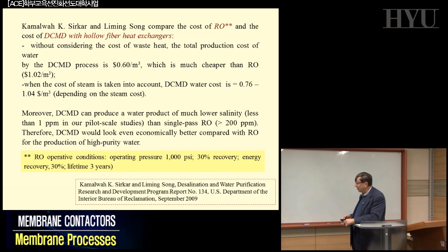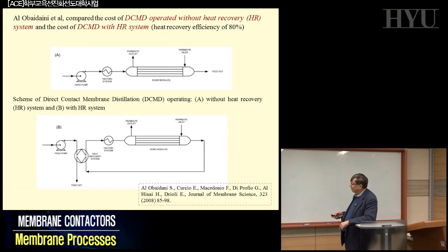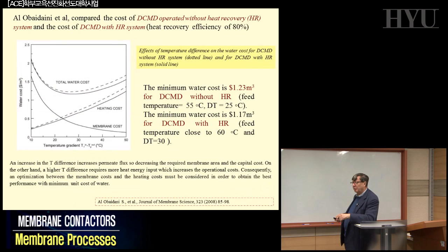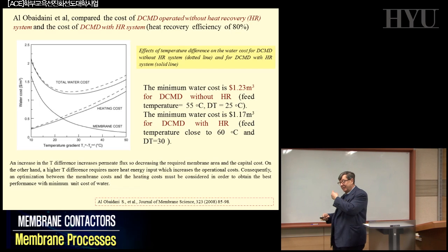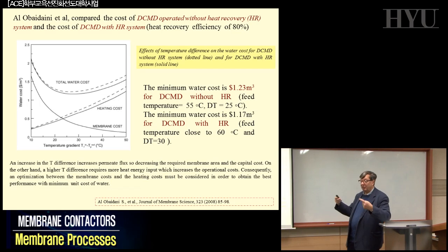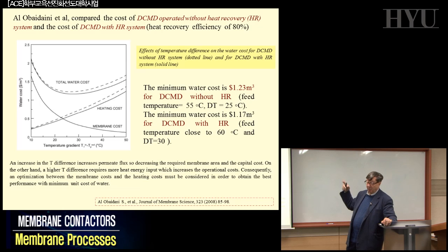And you will be able to realize what we were discussing the other time in terms of possibility to combine not only freshwater production, but also to introduce a new strategy, because when you have a 95% recovery factor, you can have a lot of concentrate available, a lot of salts. And these salts, we will see next time, will be the origin of another unit operation, very interesting and appropriate more than membrane distillation, which is membrane crystallizers.